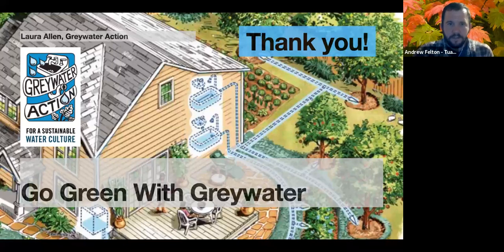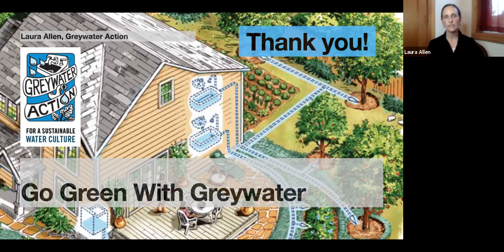Looks like we do have one. If you have a condensation pump from a high efficiency furnace or tankless water heater, can this be used as gray water to water plants as well? Condensation water, I don't know if it's classified with gray water or not, but it is a non-potable supply. At the residential level, it's probably not very much water, but I would guess yes, as long as it's not contacting some kind of metal that's leaching, or maybe just check into it a little bit.